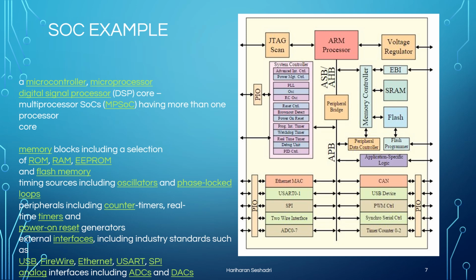And as we said, we have memory, SRAM and flash memory and ROM, right? And there's a memory controller to talk to SRAM. And the external bus interface will talk to the DRAM, which is outside the chip. It's called EBI, external bus interface. Typically we have LPDDR, that's the industry standard, LPDDR5, LPDDR6, and then comes the high density, right? Low power. That's the latest trend in the industry. This is an outdated diagram. We have a controller layer, physical layer, and then the actual device sitting on the board. People write models and they integrate, associate, and verify that. We'll see that later, right?